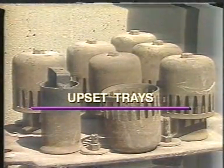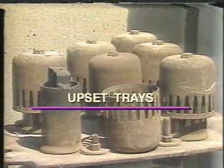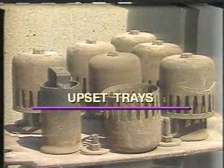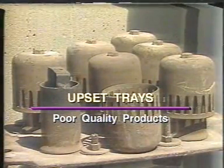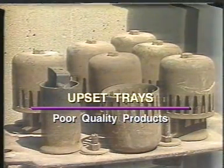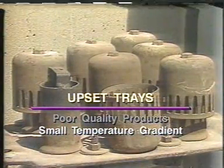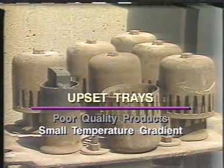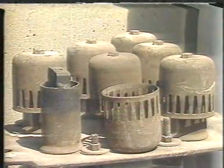Another condition that can interfere with normal operations is upset or damaged trays. Upset trays are usually caused by excessive vapor velocities, by the sudden vaporization of water, or by liquid surges in the bottom of the tower. Upset trays do not fractionate properly because vapors are not forced to bubble through the liquid on the trays. As a result, the liquid on a series of upset trays will have the same composition and will exhibit little temperature difference. Since it is easier for vapors to flow around upset trays than through bubble caps, a tower with upset trays will usually exhibit a decrease in differential pressure.